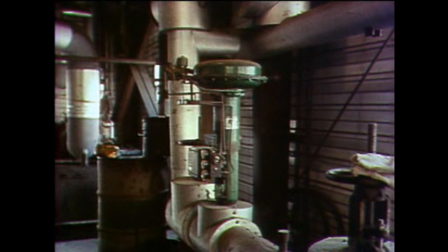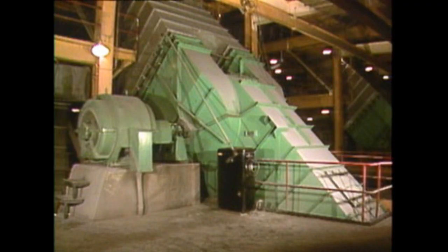Boilers using oil or gas have regulating valves that vary the flow of fuel. When the amount of fuel increases or decreases, the airflow into the boiler must also increase or decrease to ensure proper combustion. This can be done by adjusting inlet vanes or discharge dampers on the fans that supply air to the boiler, or by adjusting the speed of the fans.